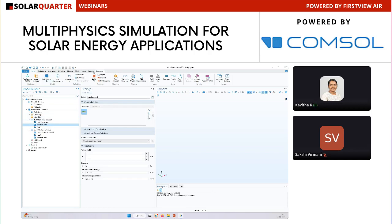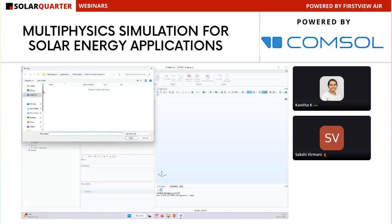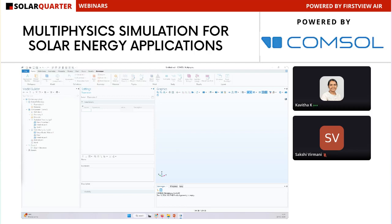And also you have a top ribbon tab. The top ribbon tab and the model builder serve the same purpose. They are going to guide you through the modeling workflow. So you can use the top ribbon tab to model your application, or you can use the model builder. The model builder follows the top-down approach as I mentioned earlier. First you will define the parameters required. You can start typing the parameters here, or you can load the parameters from a file. Let me show you an example.